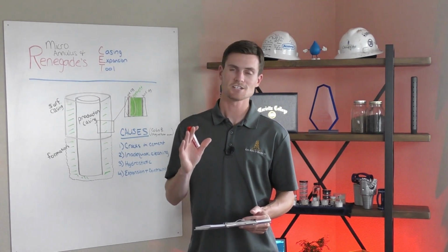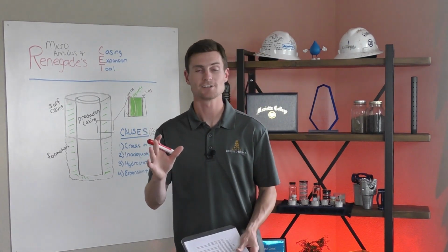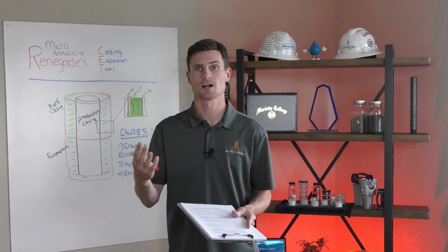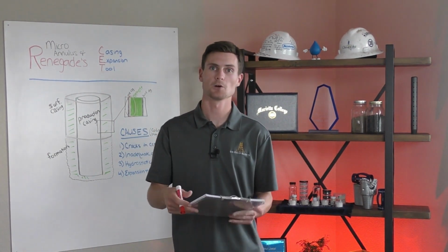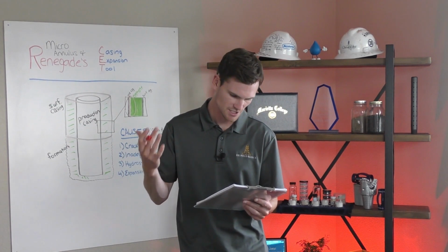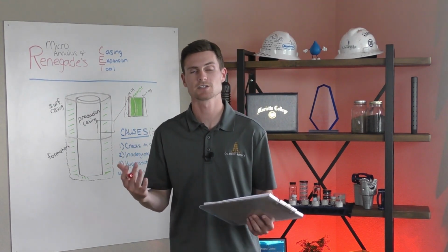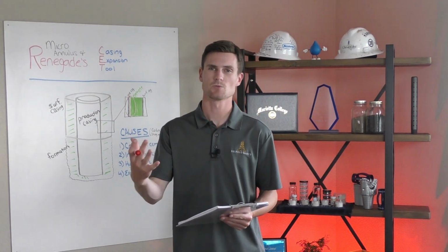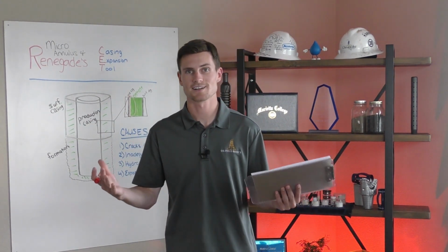So in terms of remediation, if you have not drilled the well yet and you're still in the planning stage, there are things you can do. You can use fancy cement on your primary cement job, spend a lot of money that way and hope that it works, right? So there are things such as self-healing cement and resin coated or resin cement. So there are things in the market that exist, and you might see that used more offshore. But a lot of times these are on existing wells.